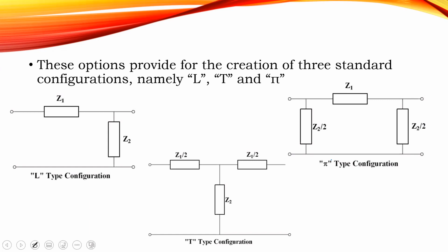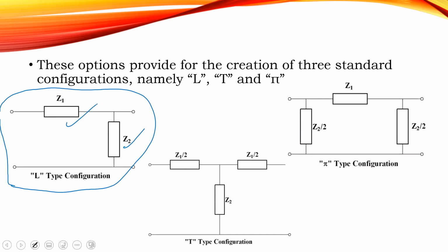And you would have been familiar with an L-section filter, right? Where, let's say you are converting AC to DC, then of course you would have your capacitor in parallel and your inductor in series. Now, let's use the principle that we just outlined to say why I would have a capacitor in parallel, because that must make sense, eh? And the inductor in series.